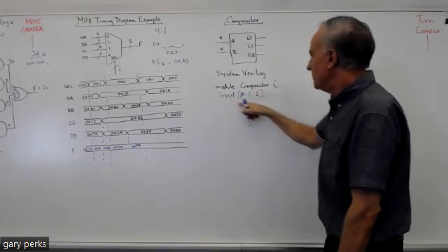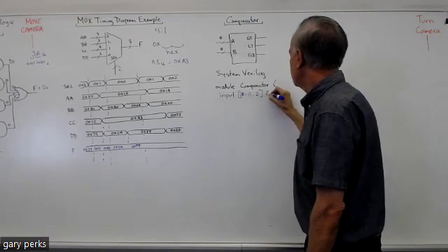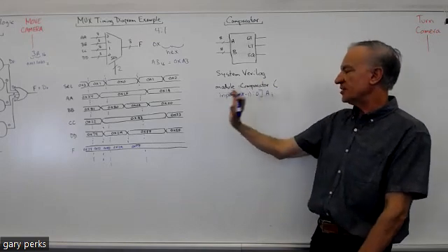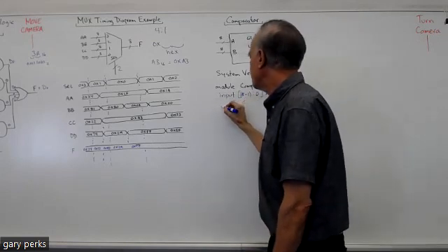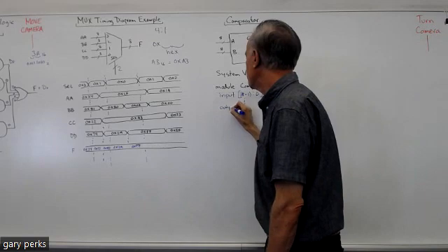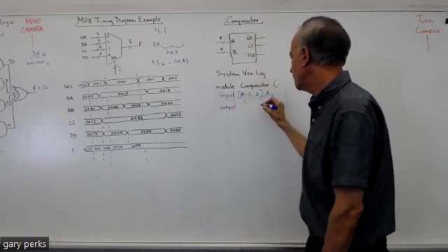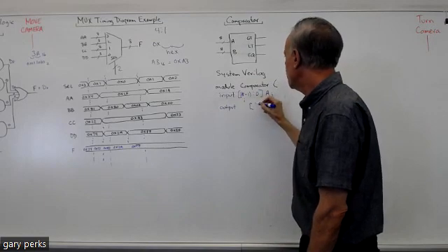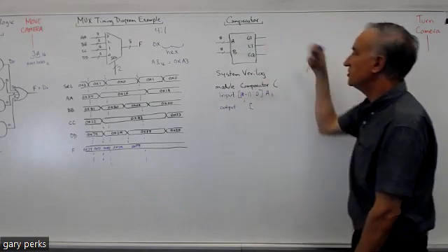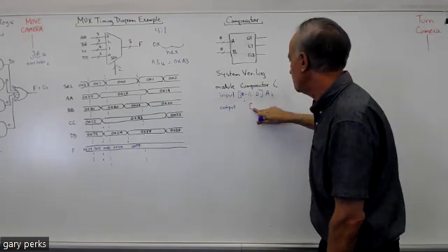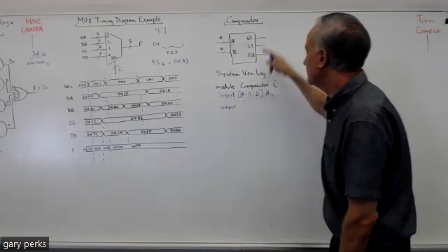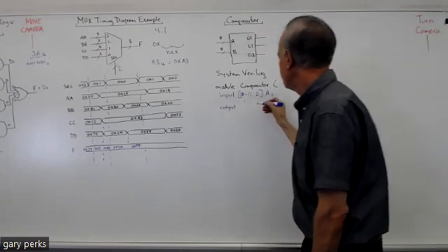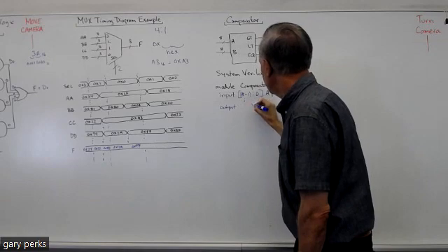And then, whatever you call it. Now, you would do this just like you've been doing, but there is one difference that has to do with the output that I'm going to come back to in just a second. So I'm going to write output, and over here, I'm going to leave a space. And then over here, I'm going to put the same thing. Well, here our outputs are just single bit, so we don't put the bracket, right? Because our outputs GT, LT, and EQ are all single bit. So I put GT.